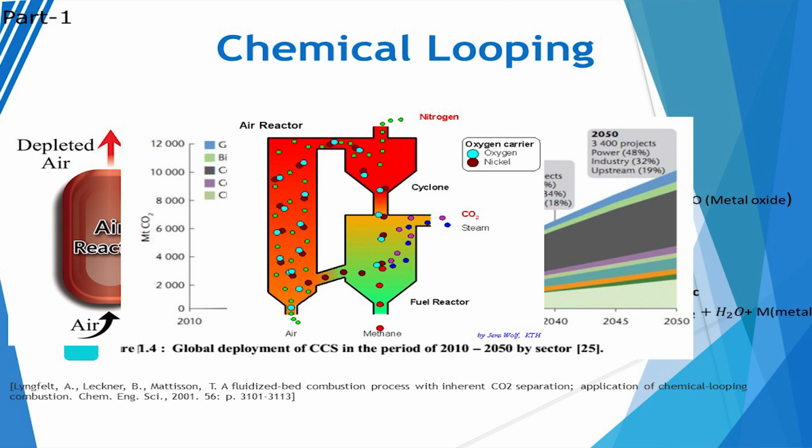So in this chemical looping system, which oxygen carrier materials play the main role? Nowadays, they are using natural ores. Among natural ores, ilmenite is very common. Ilmenite is a combination of iron, manganese and titanium, mostly these three components. Some ores, like Egyptian ones, are very common and give better results in this chemical looping system. They are based on iron and titanium. Some Canadian ores have an iron manganese base, but there are some impurities.